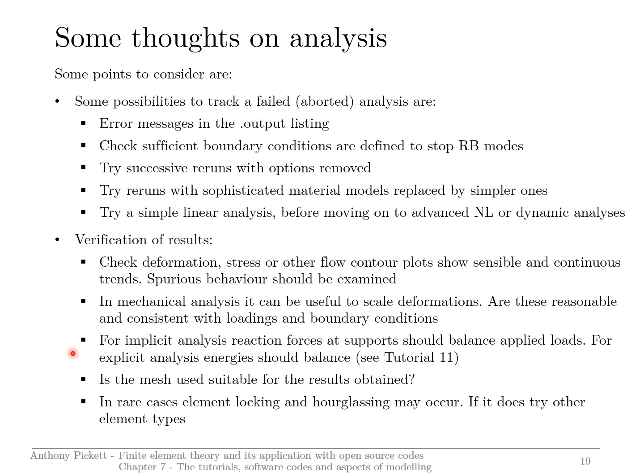If you're doing an explicit analysis, the energies should balance. In other words, the energy from external loading plus the energy from internal deformations and plasticity should equal total energy and should be constant.